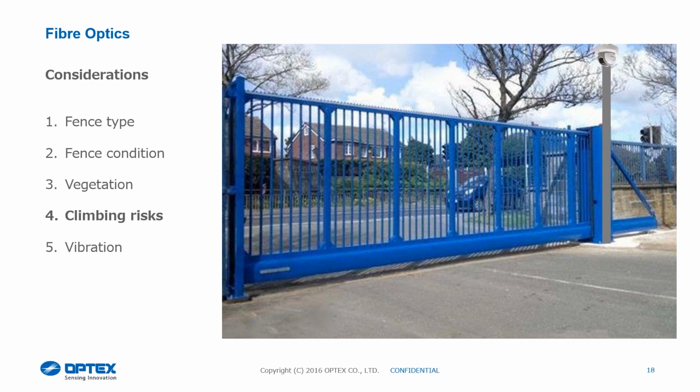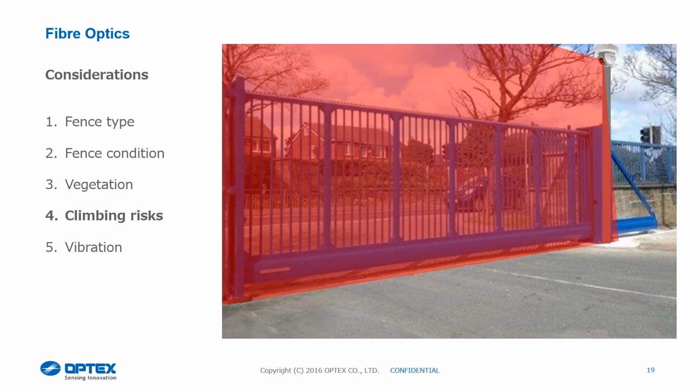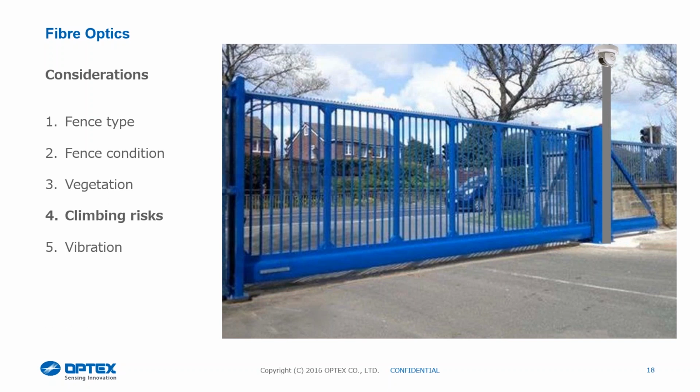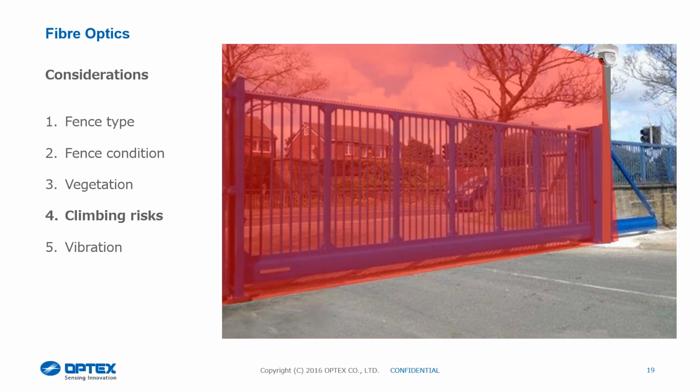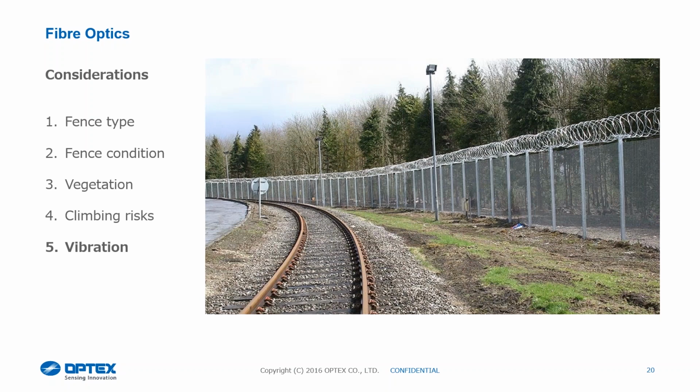Underneath the gate is not always level and nice and tight like that, so you can have undulating ground level or slopes, and potentially that could be somewhere that somebody can crawl under. And then the last part is the gate post itself. That kind of gate post, a big solid foot by foot wide gate post, again, it's quite easy for somebody to put an A-frame ladder on there and climb over the top. So what we can do with that is look at the laser technology that we'll come onto later on, and we drop that laser technology onto there, and then we just give you a blanket of coverage across that gate, and then we can cover all those applications for somebody going under, over, or using the gate post.